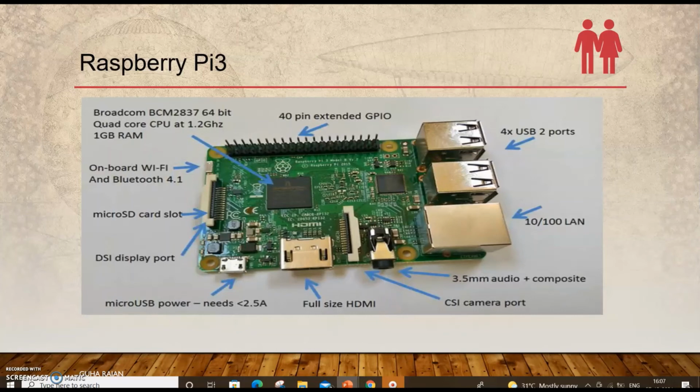On power on, it's a kind of microcomputer board plus the GPIO pins, because in a computer you will not have this GPIO pin. That is where you cannot connect sensors or actuators, such as a switch or relays, if you recollect correctly. You cannot connect them with the computer, whereas with the GPIO pin you can. And because Wi-Fi is there, you can connect it to the cloud as well. So in a way it will be a complete Internet of Things board.